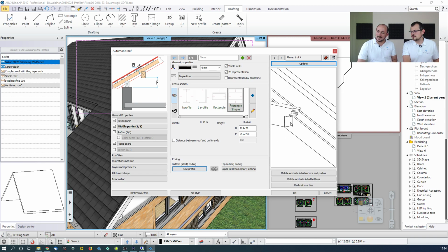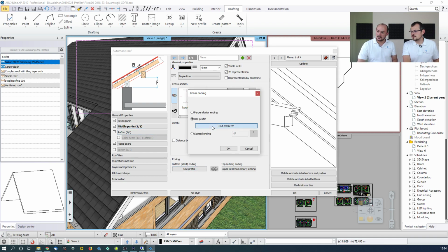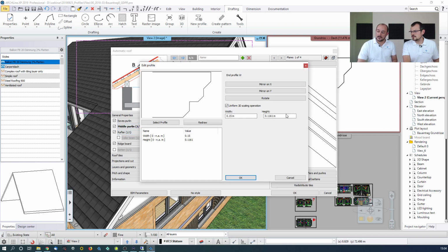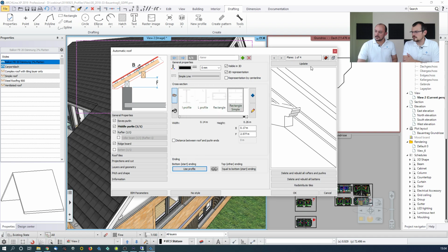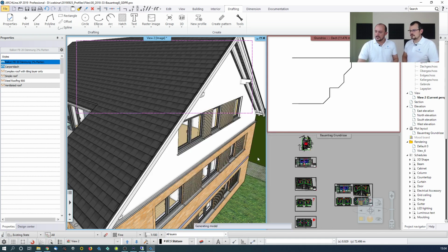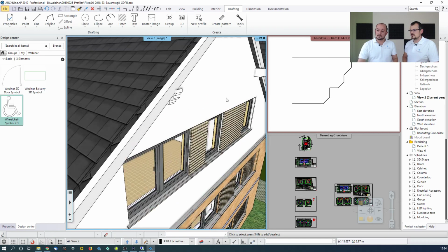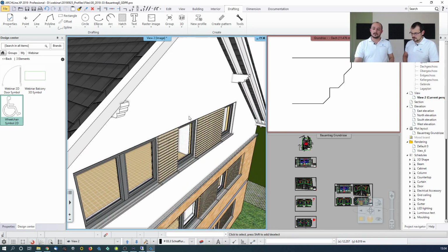So it's very, very tiny now. Again, you can just change it to something else. This is where you can change its size. You can skip this part, for example, and say you would like to change its height, or you would like to uniformly change it to double the size. Okay, okay, and okay. So now update, and now it's larger. So this is how you can scale it. And then you say okay, and it appears in the design, and from this point on it goes for all the renders and all the elevations and everywhere.